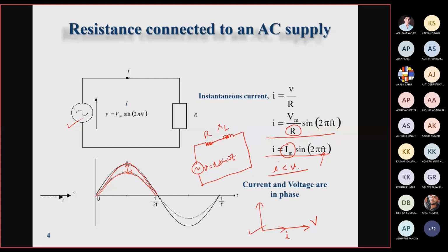By the same procedure, suppose we take the voltage across the resistor, VR, on the reference axis. This is VR, the voltage drop across the resistor R. And we take VL as the voltage drop in the inductor XL having inductance L. For this resistor, both voltage and current will be in the same phase, if I is the current flowing through the circuit due to the voltage source V. So both VR and the current will be in the same phase, as we have discussed for the previous case.